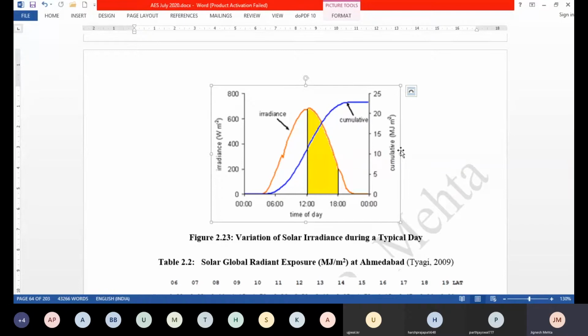So what is joule per second, and when you measure it over an hour, if you are taking a reading at each second, then the average of that whole hour may be multiplied with 3600 seconds, then you will get it in joule per meter square, and then you may convert it into kilojoule per meter square or megajoule per meter square, and again you go on adding it for multiple hours, and finally one might be interested in the total energy that was available per meter square area in the whole day. So that may be expressed as megajoule per meter square.